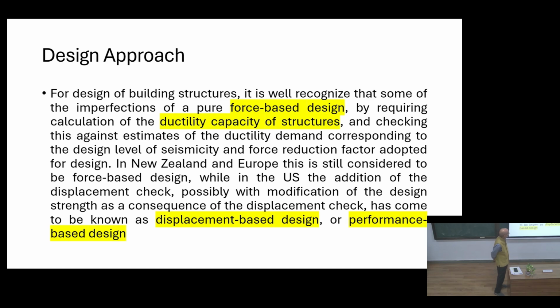Now, the code designs we are doing, and in practice also, are force-based design, because force is taken as the predominant thing. When you design for force, you use partial safety factors and bring it down. So it is not only the elastic range you are designing for; that is precisely a performance design in the force-based approach too. The level you fix is something else, and then you allow non-linear deformation in the structure. So the force becomes the basis.